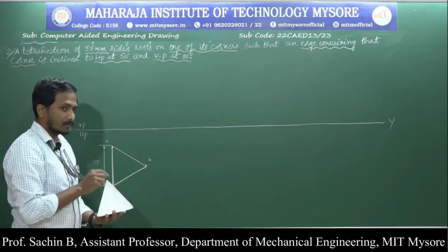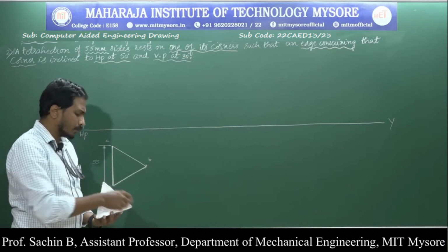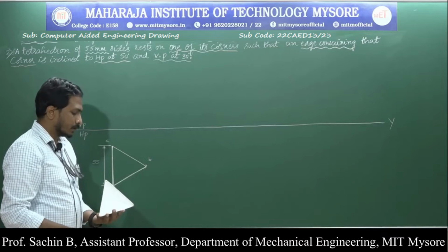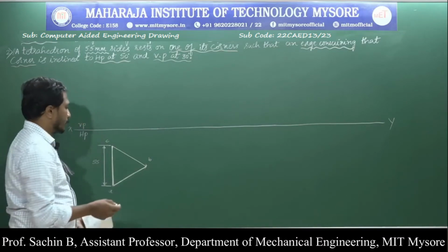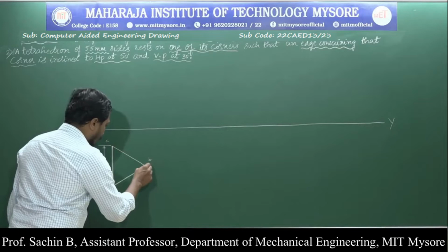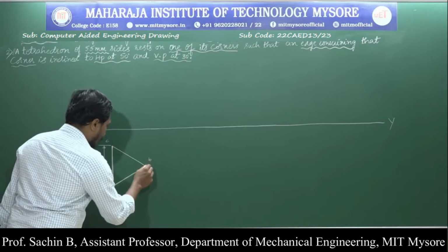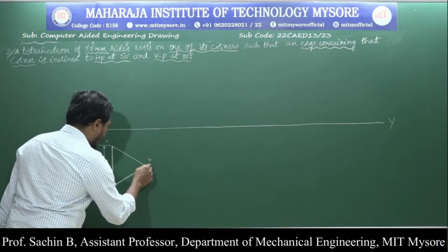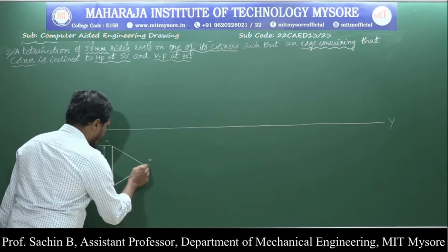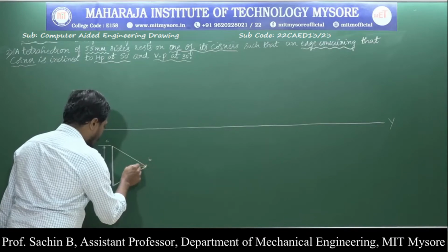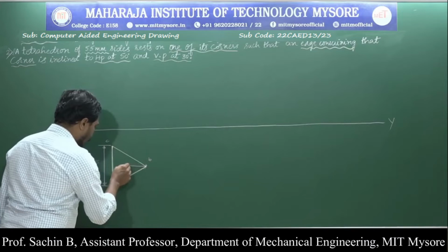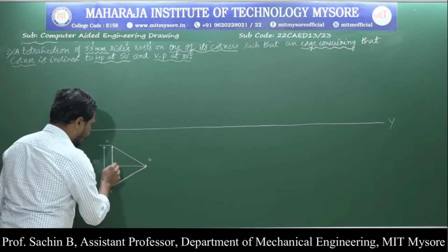From the top view, these slant edges are clearly visible to us. To get them, first from corner B, I will draw a thin projection line that should meet the opposite edge midpoint.